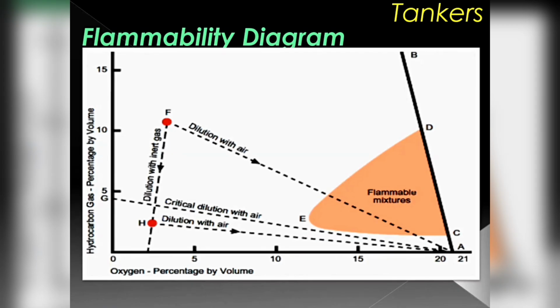Sir, one more doubt, sir. Suppose we are given a product and its upper and lower flammable ranges. How can we draw the E point for that, meaning the whole flammable range for that? Suppose the lower flammable was 5%. It will fall somewhere here. Just draw a line parallel to the x-axis, and where it is 11% and cutting here, that becomes point E.